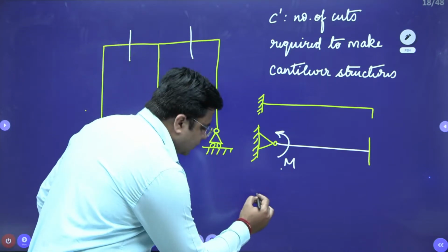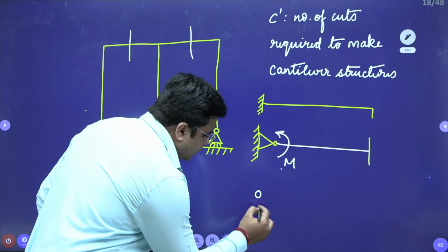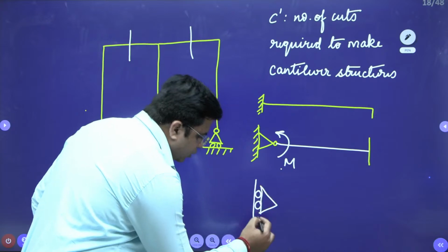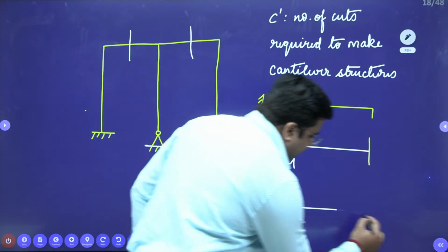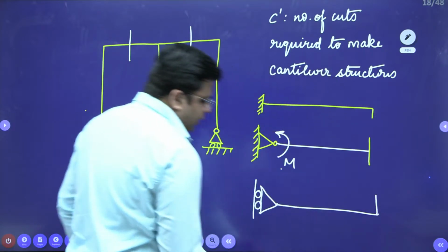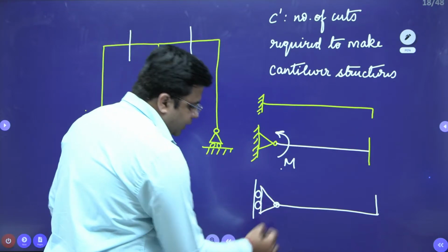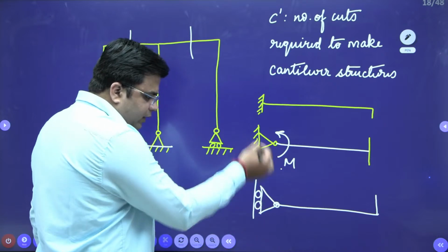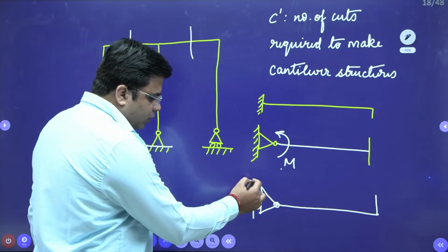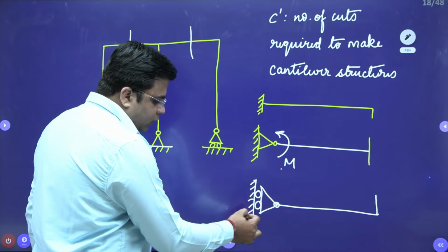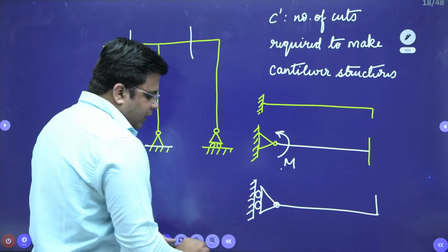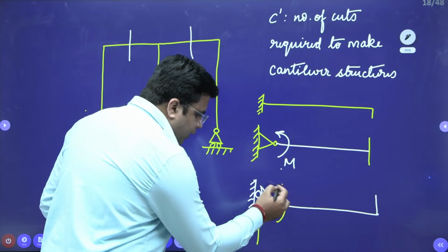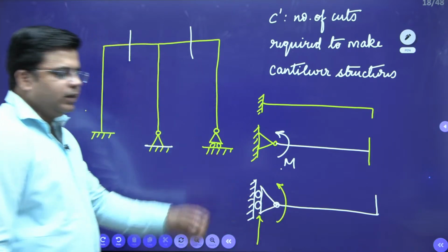When you look at the third variety, you have this roller support. For the cantilever that is formed, this roller support, due to this hinge, can move the structure, and it can also move in this direction where the roller support is attached to the surface. So, in order to restrain this, I need to apply one reaction and one moment to keep the structure in a stable position.